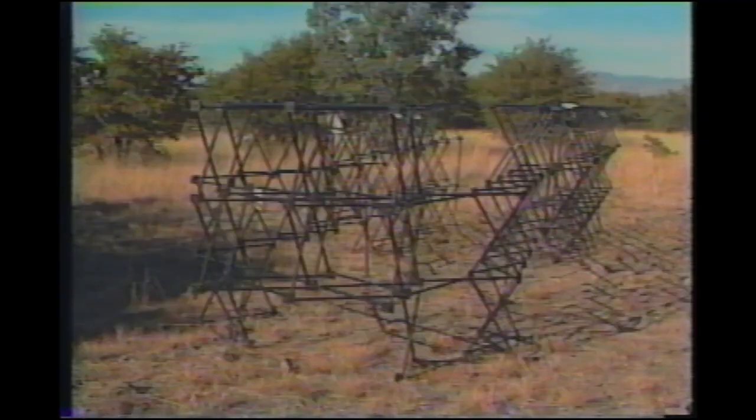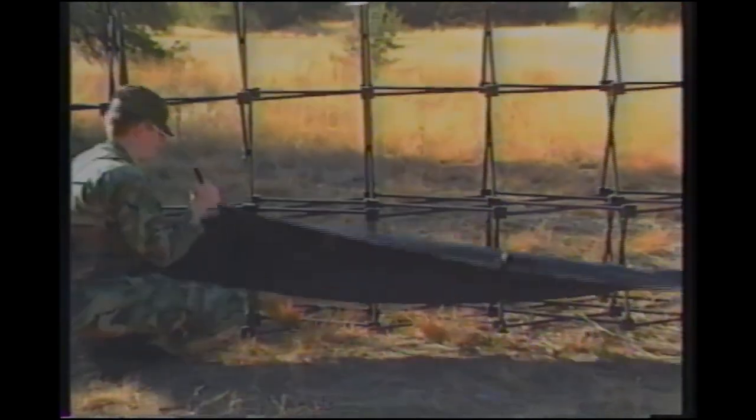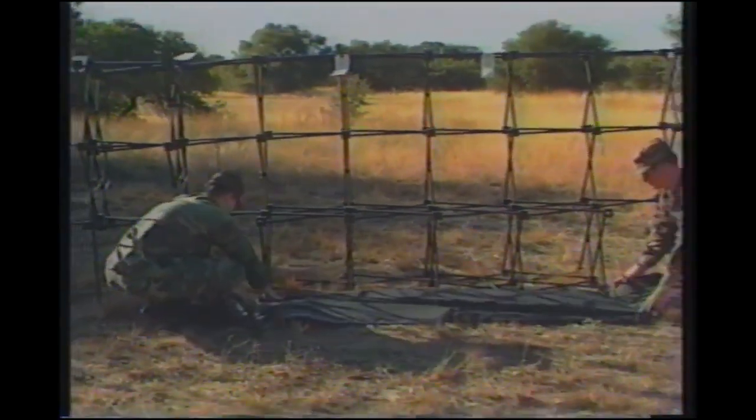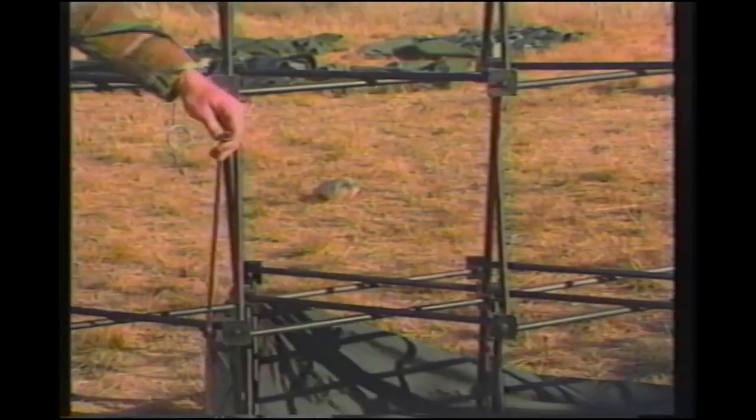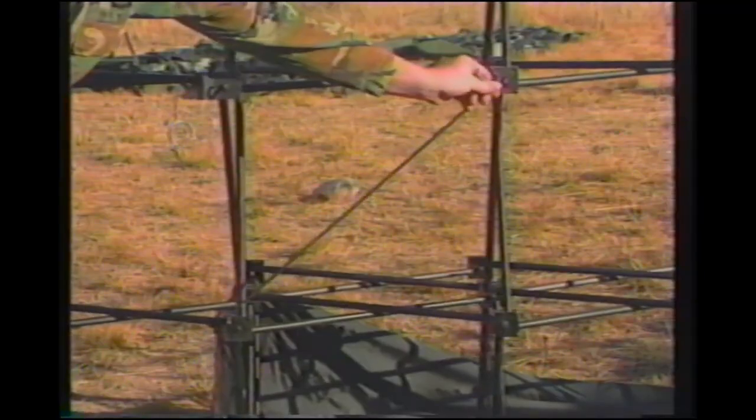The front and side frame connection should look like this when properly connected. Now, install the rear right side inside wheel skirt. You do this by hooking the 3 grommets at the bottom edge of the skirt to the hooks on the frame. Be sure to attach the stretch cords at the top edge and the ends of the skirt to the frame.